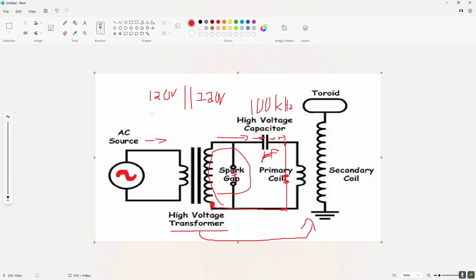But one of the cautions was that you never wanted to touch the chassis of that radio when it was on, because they didn't have any transformers in them. That means they didn't have any isolation. So transformers not only transform your energy, but they also isolate your energy.